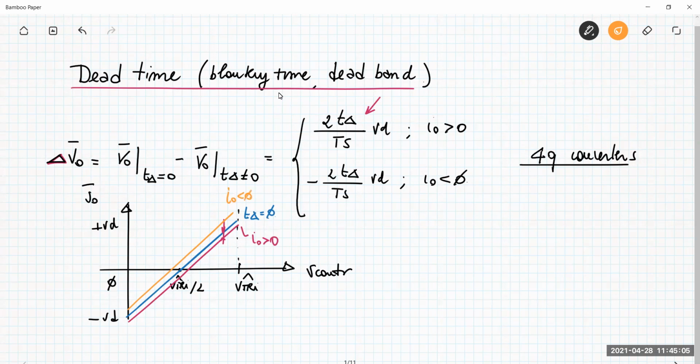Okay, so now the difference becomes negative. So dead time is something that leads to an error in the average voltage. Feedback control can help to avoid this difference by selecting the correct duty cycle to recover this error. Okay, so this completes the discussion about the dead time as a derivation from the half-bridge discussion.